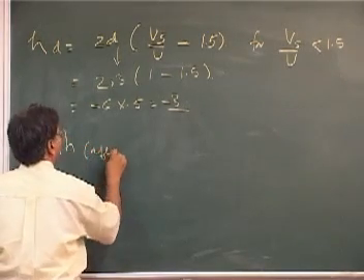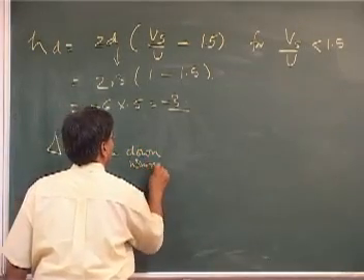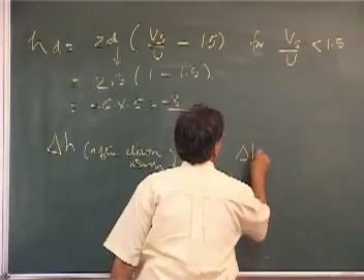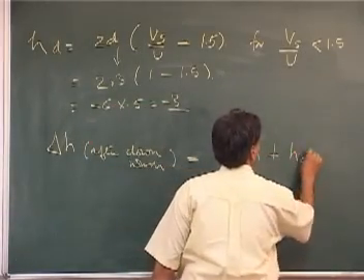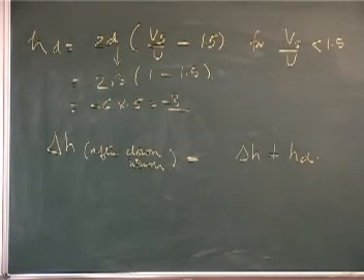or the final delta H after downwash equals delta H that you have calculated above plus HD. Does that make sense now? So your effective plume rise will reduce because it has been subjected to aerodynamic downwash. That is why you see that factor coming out to be negative. Alright, clear?